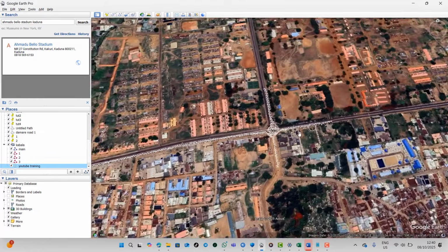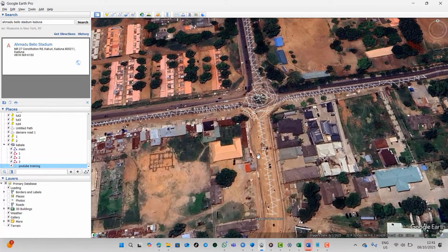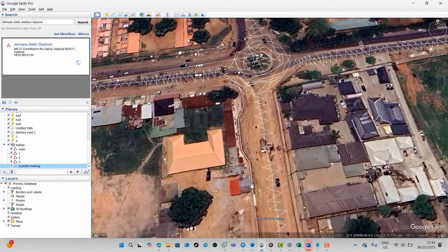And you know, I mentioned there is right of way. For highway, we have right of way, right? Which used to be 30 meters, but I learned that it is 47.5 meters now. So you can go as far as measuring from this to know what distance you have. It is very, very important. But this is not like a major highway per se. So these are the key information that you should take note of when you are doing your road design.